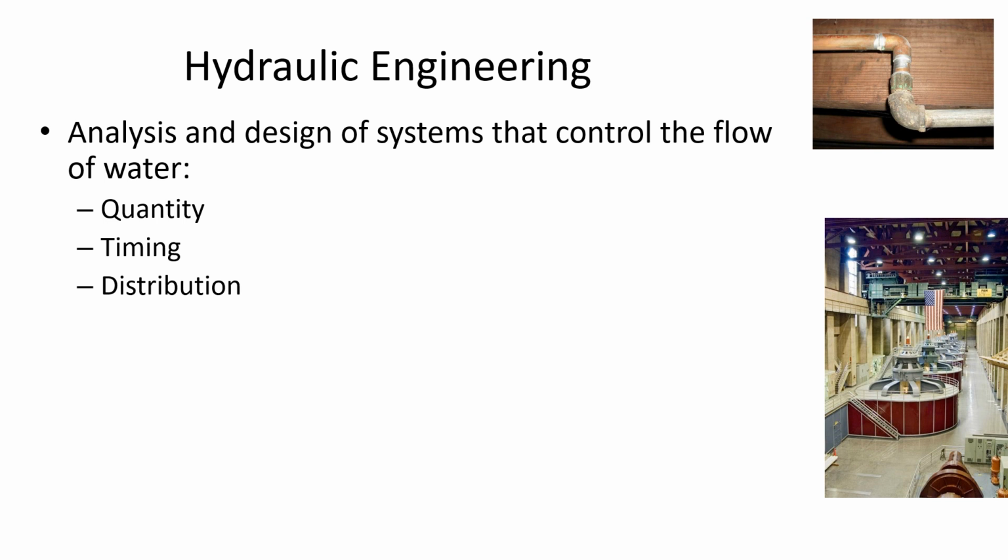And of course, a large pipe would be expensive because there's a lot of material there. It would be more costly to install because the fittings would be more difficult and there'd have to be more trenching. So it's a balancing act of providing enough pressure downstream, making sure that the pipe is large enough, but not spending too much money. So it's a balancing act, and that's what you're going to do in your design project, is that iterative process of trying to make the pipes as small as possible, but still providing enough pressure downstream.